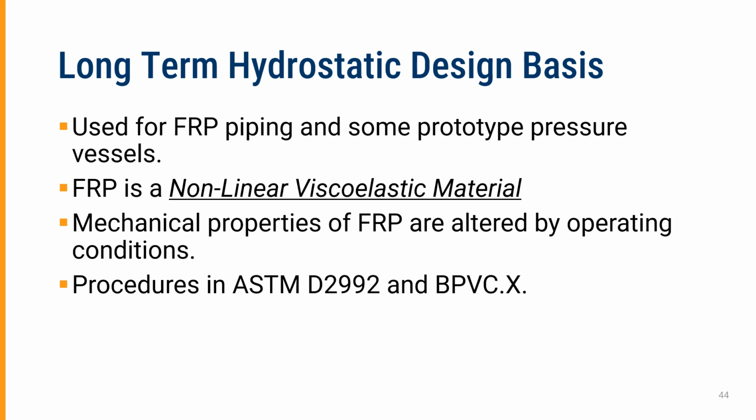The long-term hydrostatic design basis is fairly unique to FRP materials. It's used for FRP piping and some prototype pressure vessels. For example, the reverse osmosis vessel that I pointed out earlier is actually certified using long-term hydrostatic design basis principles.